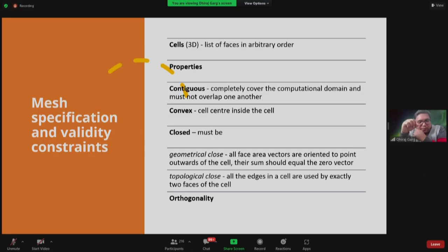There you will see each edge is a part of two attaching faces, so that ensures that it is not open. The cell is closed. If an edge is shared by more than two faces on one side and one face on another, then we create an additional point at the meeting point and create more edges instead of one single edge, so as to avoid this issue.